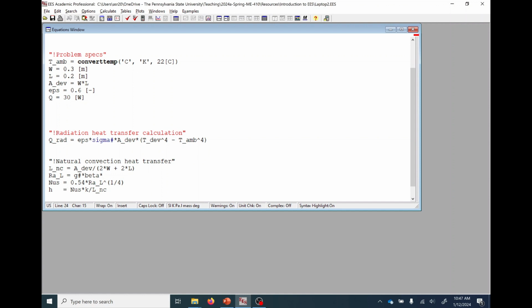You don't need to know this yet, but just to complete the problem, let's step this through, times the temperature difference between the surface and the air around the surface, so that's going to be T device minus T ambient, times the length scale for natural convection cubed, divided by the kinematic viscosity, which is a material property of the air, times the thermal diffusivity of the air, which is another material property.